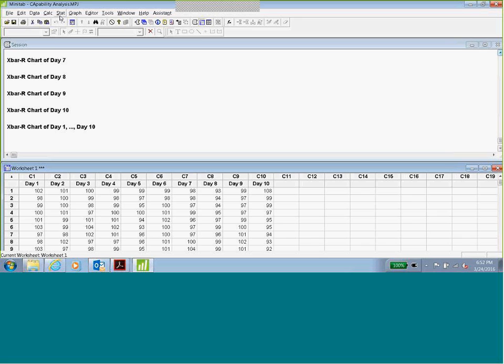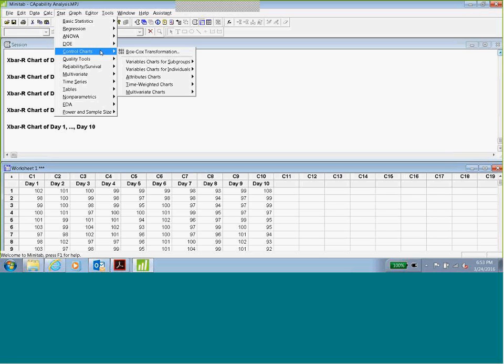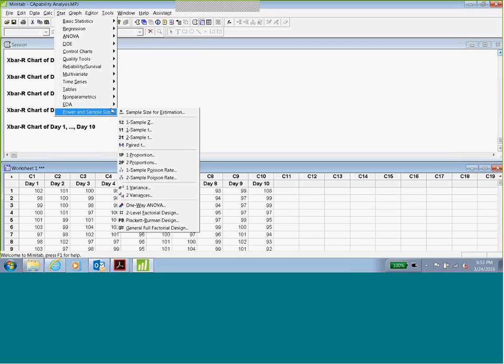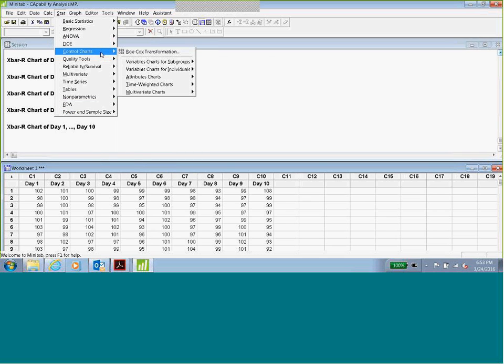Okay, things can happen. Depending upon how your quality or process validation engineers want you to do it, accordingly you're going to use Minitab or another statistical tool to plot the control charts, and from the control charts you can determine if it is a stable process or not.